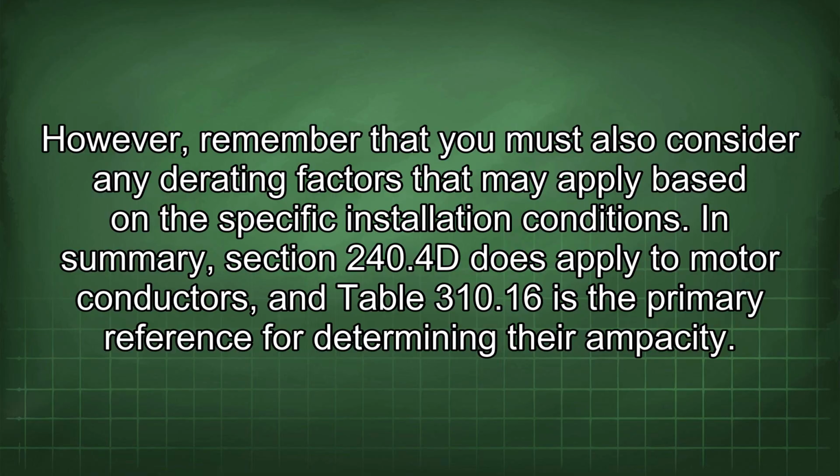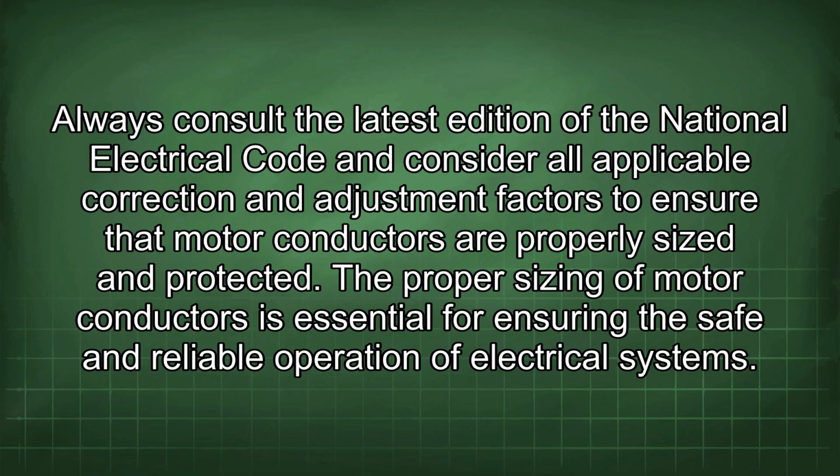In summary, Section 240.4(D) does apply to motor conductors, and Table 310.16 is the primary reference for determining their ampacity. Always consult the latest edition of the National Electrical Code and consider all applicable correction and adjustment factors to ensure that motor conductors are properly sized and protected.